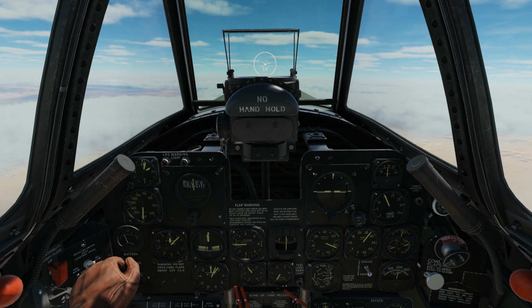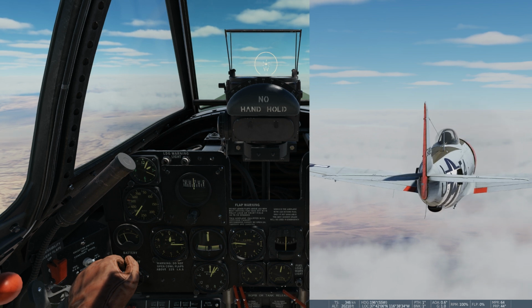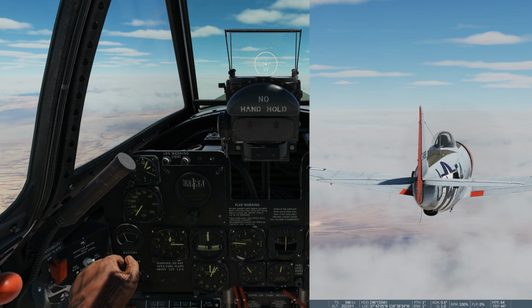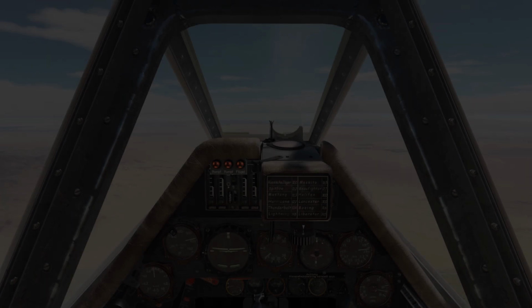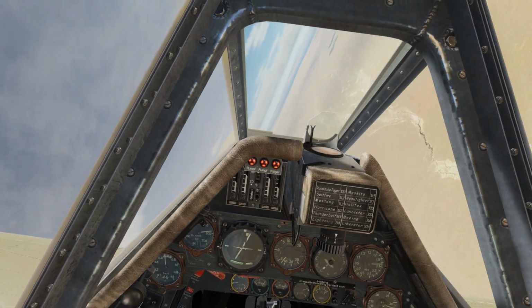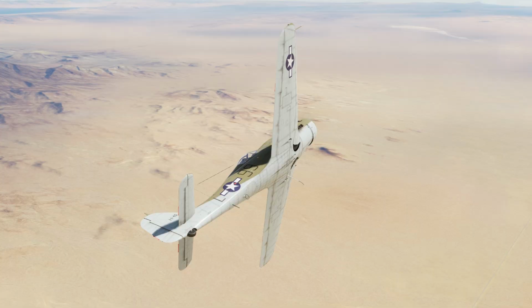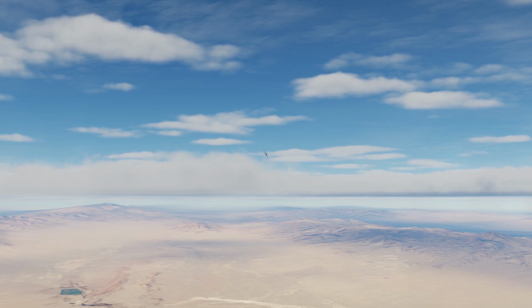Now that you have some understanding of the first two, let's learn about the next one, equivalent airspeed. As you start picking up speed at higher altitude, you may notice that your indicated speed is higher than it should be, and that the center of lift is moving further out. This is noticeable when the plane requires more and more nose-up trim as your speed gets higher. This is because the air hitting the pitot probe, and at the leading edge of the wing, will get compressed, and the stagnation point in front of the wing will get closer to it.